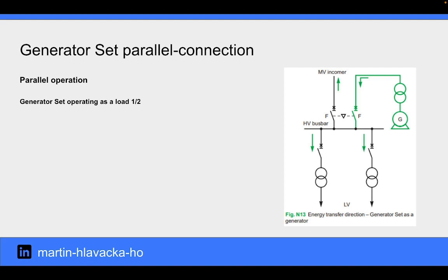This may generate overloading of the other generator sets and thus place the electrical installation out of operation. To check that the generator set is supplying the installation with power, the proper flow direction of energy on the coupling bus bar must be checked using a specific reverse power check. If the fault occurs, this function will eliminate the faulty set.